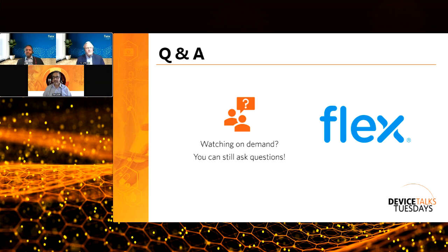Yeah, and often they're ones that you might look at and think, well, that's just endemic. And then the model will help you understand why they actually happen. They're not just because. That's the goal. Models are really good at things that are hard to figure out just on paper. They look at how things interact. If you have longer times, say on one event, on one machine at the same instant, when you have a shorter time on the next one downstream, you've just lost capacity. That's really hard to do when you're trying to work that out on paper. But a model can show you exactly what happens there.